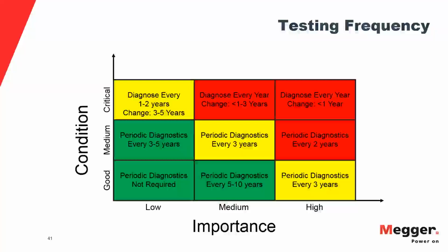By noise, do you mean in the audio domain or high frequency noises? No, very much not audio noise. By noise, I mean signals in the range that partial discharge would be present, which is some hundreds of megahertz. Corona is very similar to partial discharge. So if you're in a switch yard and there's some corona going on, that can induce signals into your test equipment, things like that.